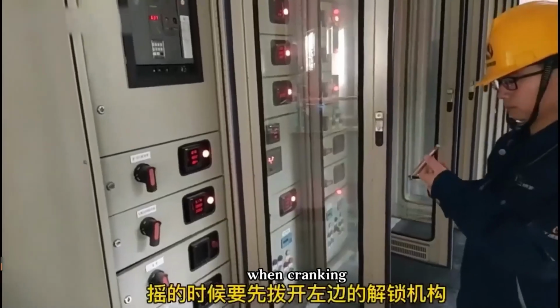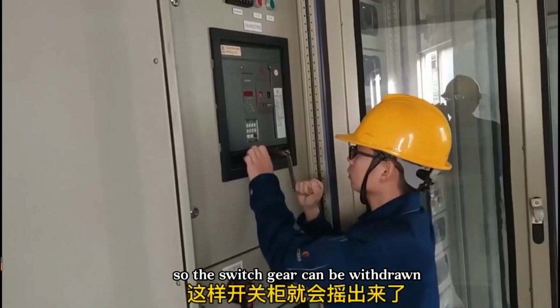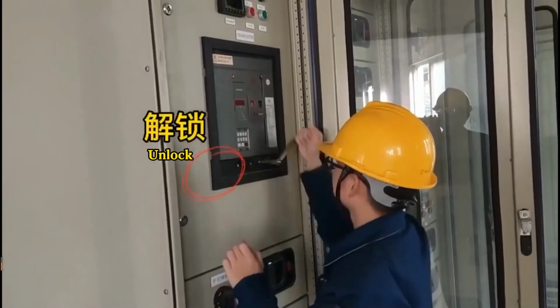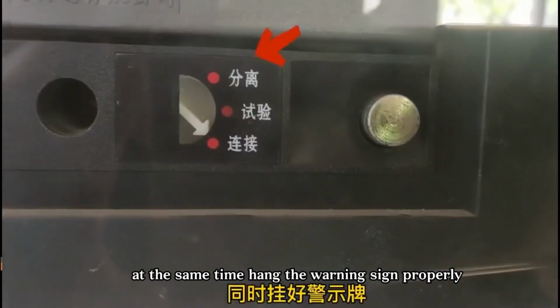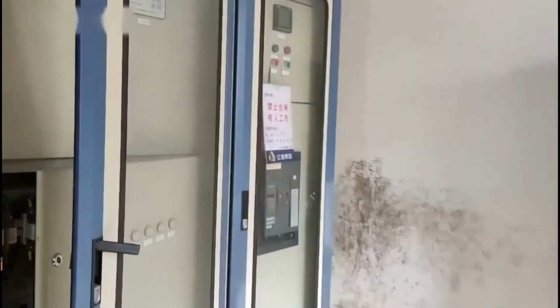When cranking, first release the locking mechanism on the left, so the switchgear can be withdrawn, and it must be cranked to the disconnected position indicated by the arrow. It must never be loosely connected. At the same time, hang the warning sign properly. This completes the power-off process.